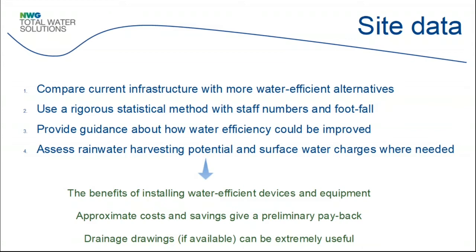And it's because the valve and the float switch on the valve from the mains was broken. So they were literally taking water from the mains, it was going into the rainwater tank, and then it was overflowing and going down the drain. So they were almost literally throwing water down the drain. And that trend had been picked up in the billing data, but it wasn't apparent to the school. So that's one aspect of how this sort of desktop audit can help you look at rainwater harvesting.